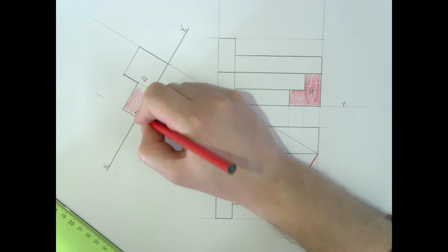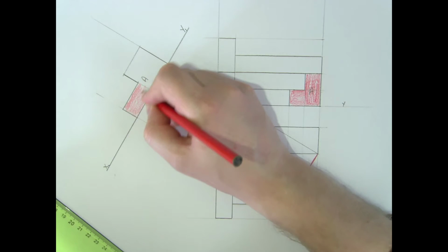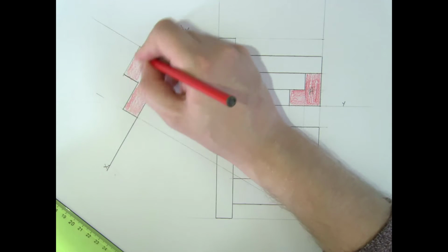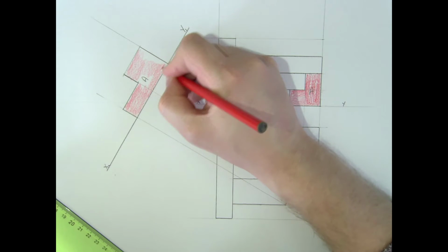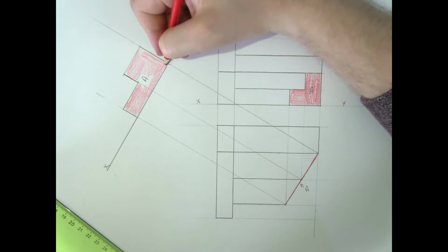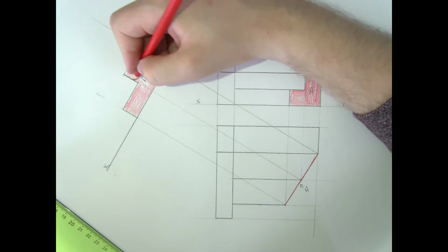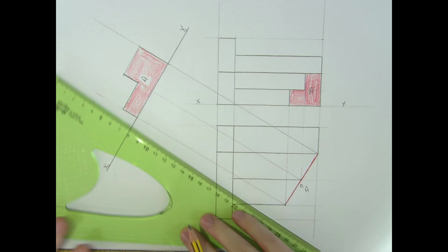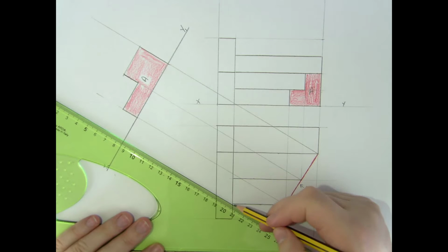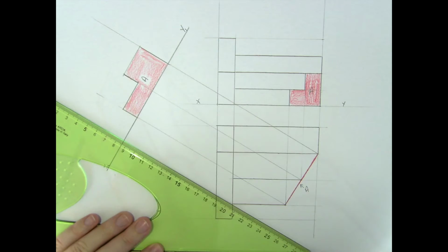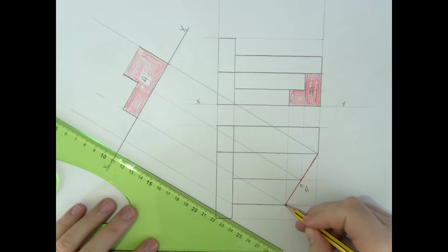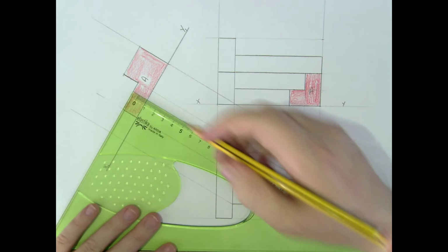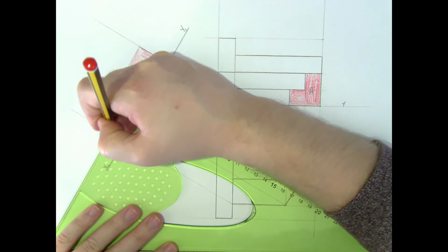We still need to find what the rest of the object looks like, the structure looks like, in this auxiliary elevation view. And to do that, we're going to do the same method that we've just used now. So taking each point in turn, projecting them up and finding their height in the elevation. So taking this point, that's going to come up along here. That's the front edge of our step. So it's at both the ground and it's up 15 millimeters. So this is up 15. I can extend that on to meet it.